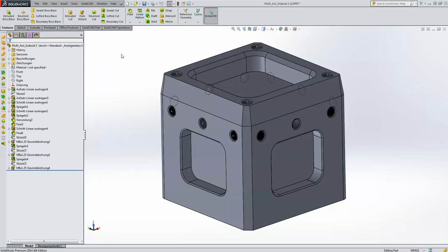Now, I particularly like to work from the center of the part. And you'll see why a little later on. So in this particular case, I have my planes over here. My main planes are actually going through the center of the part itself, so I can use that. If I didn't have a surface over here, I can easily create a surface by just clicking on top over here on the option